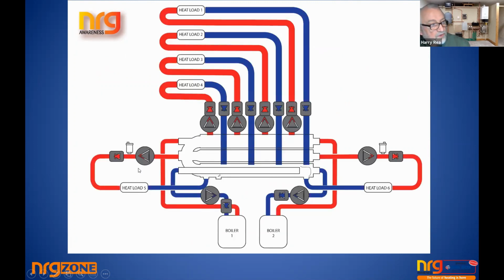Again, here we're back where it's just upside down. So remember, you do have to protect against heat rising on the returns, but that will work away absolutely perfectly. So you could put a manifold at a ceiling, say if you're in a basement boiler area, connect up onto it, and you're still feeding, well, not even at a ceiling, like say 2/3 of the way up the wall. And so you can make a very, very neat situation with the boilers underneath, feeding into the sides, and you've got your zone. So again, the imagination opens up to what you can actually do.